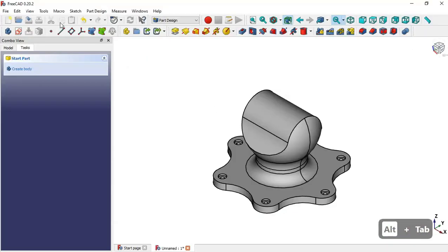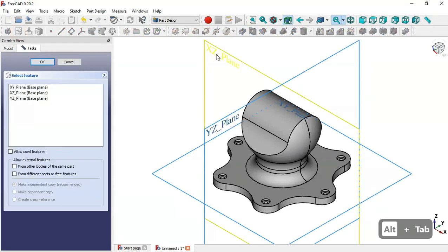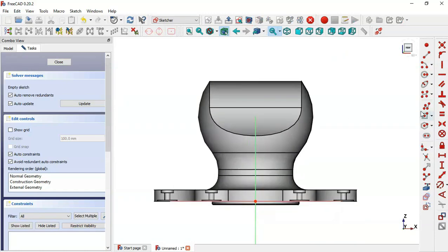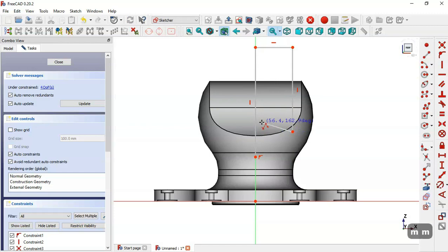So what we'll do here, we create a new sketch in XZ plane. Okay, switch to section view and now here select this line tool and select this polyline tool. Okay, here we draw this vertical line and now this horizontal line and now this line here and press M 3 times and get this arc here and now click in this point.